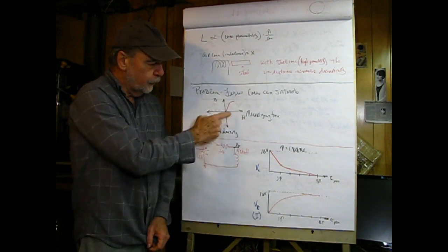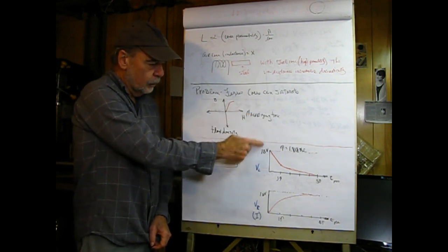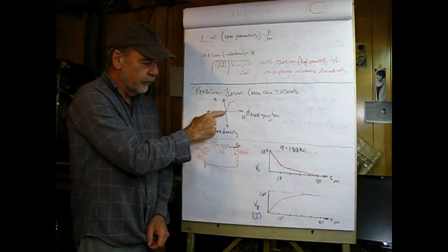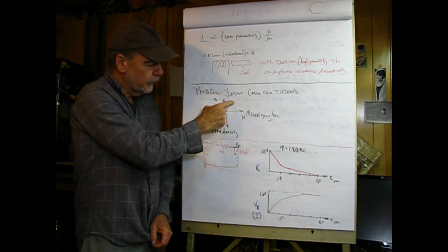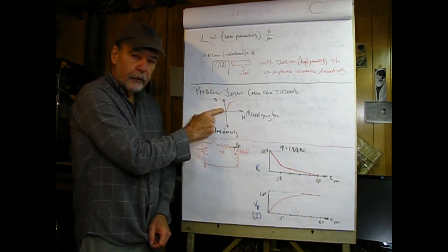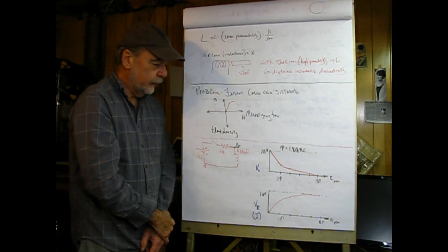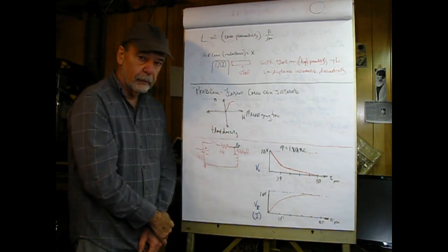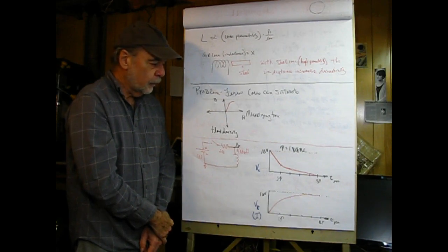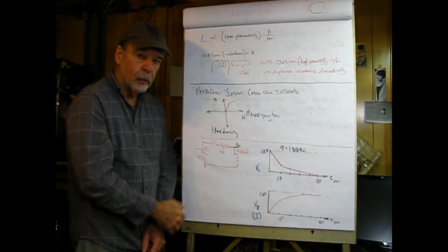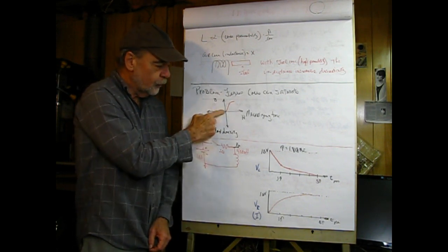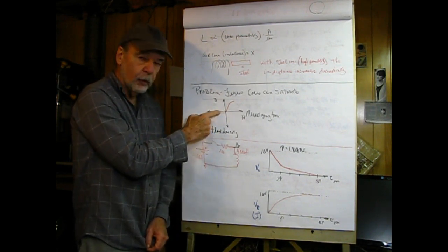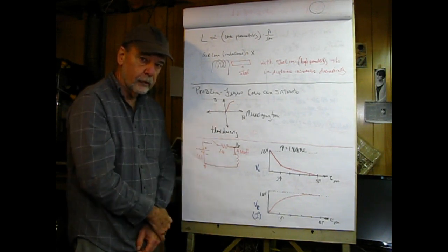Further, if you reduce this, now we're going to reduce the magnetizing force, and you think you'd end back up at the origin, but you don't. You end up over, in this case, here somewhere. Coming down, yes. So what we end up with is a slight permanent magnet after we would do this to something with a ferrous core. So the permanent magnet part of this may be good, that's what you want to make, and it may be bad if you're working with this in a circuit, because you have to apply a magnetizing force in the other direction to get the flux back to zero.